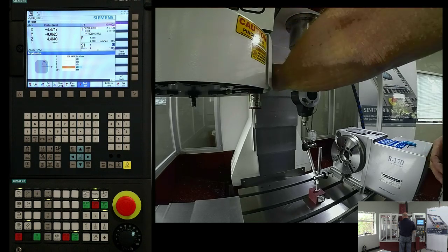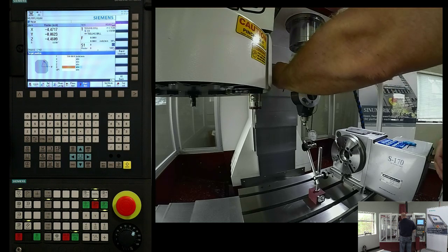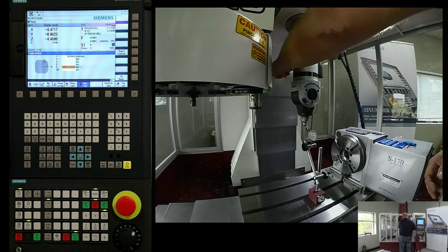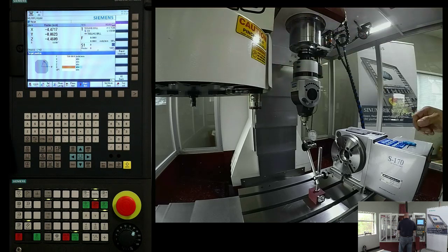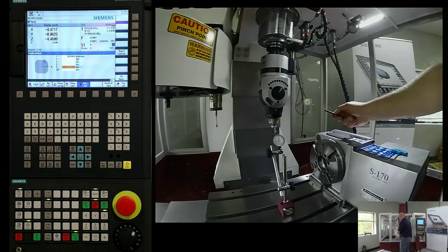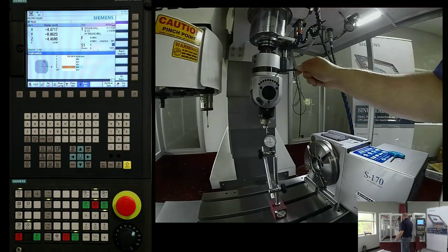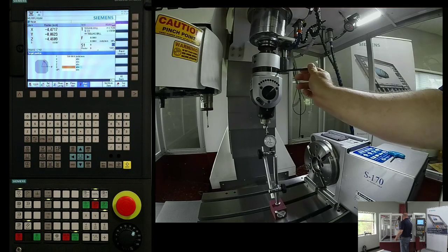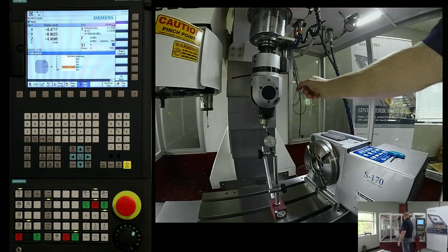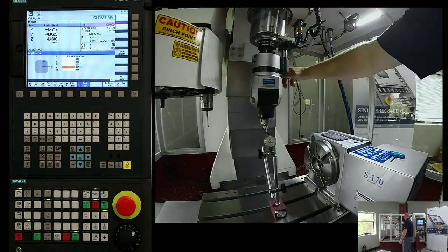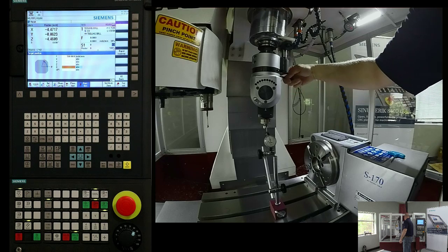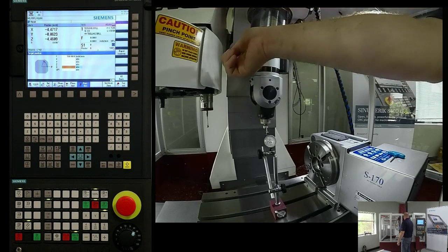Keep in mind, I haven't rotated the C up till now because I previously squared this up for time's sake. So if I was going to do that tooling ball check at a bunch of orientation points around C and B, this would have to be compensated for. If you watch the indicator, I know it's kind of hard to see, but I'm at 180 now. If I rotate around, go to 0, I actually have 2 thou of runout. And as I go all the way around my 360 degrees, I'm getting runout.